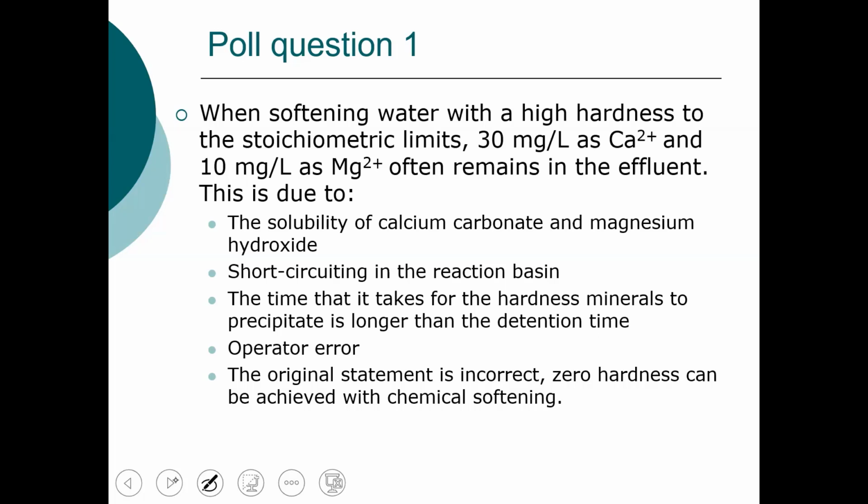One, there may be short circuiting in the reaction basin, and that can be a cause. And then, unlike acid-base reactions, precipitation reactions take time.